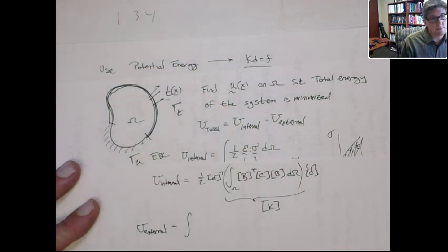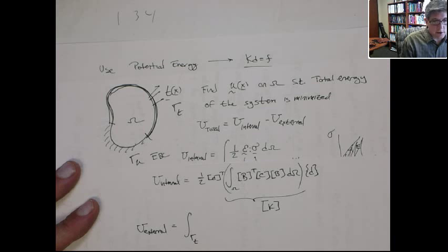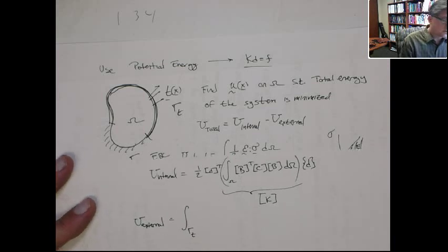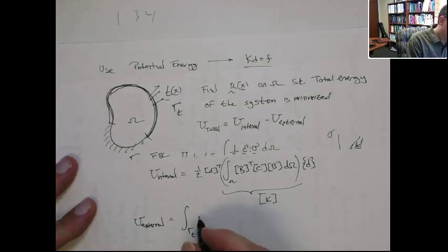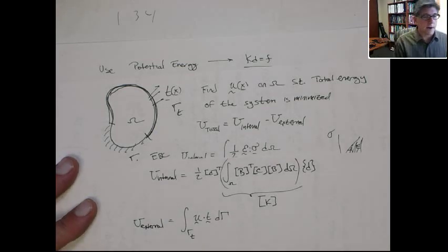So that natural boundary, that traction boundary condition, gamma t, okay? And again, we're going to consider just 2 dimensions, so we can write this as, well, the simplest way to think of it is the work is the displacement dotted with the traction. Now this is a surface integral, so I write it as d gamma, okay? All right.